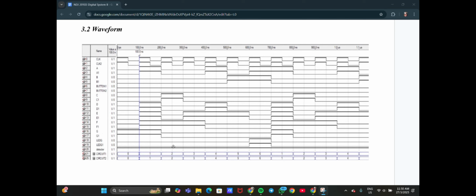each player. Since the circuit uses a 7447 BCD decoder, the output logic is active low. This means that when a signal is 0, the corresponding segment of the 7-segment display is turned on. Conversely, when the signal is 1, the segment remains off. The waveform reflects this behavior, where a 0 output means the respective segment is lit up, forming the correct numerical display corresponding to the dice value.